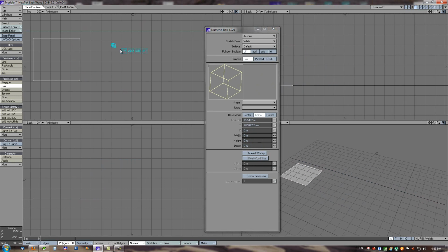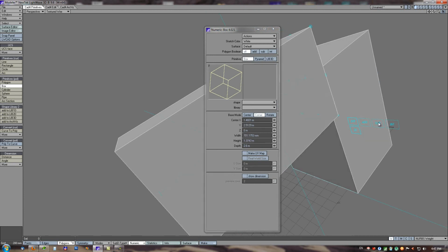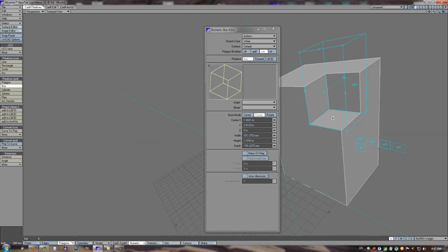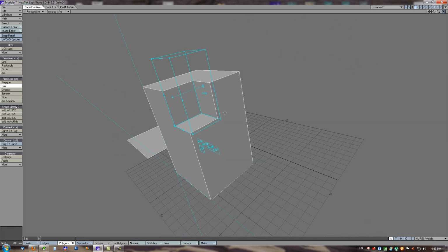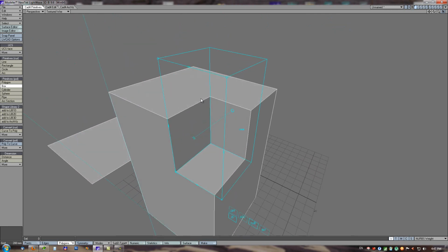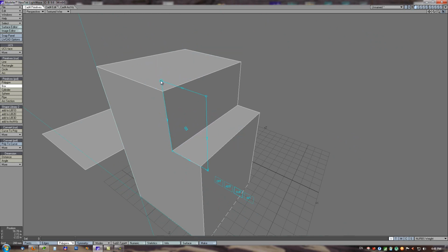When we are doing some boolean, for example, subtracting, and we have this tool in 3D mode, we are doing a subtract operation between this active box and the box in the scene. With clicking to 2D mode, we are switching this tool back into 2D mode, and the tool is now drilling the whole scene.